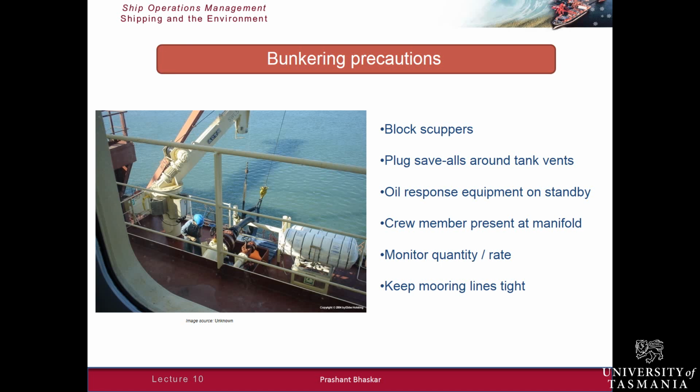Somebody should be monitoring the quantity and rate just to make sure that the oil is actually going where it is meant to go, and making sure that the ship's movement is not excessive. That is assuming that the ship is tied to a jetty, making sure that the ship doesn't move too much, otherwise the connection at the manifold between, say, the bunker barge or the ship, can be broken.